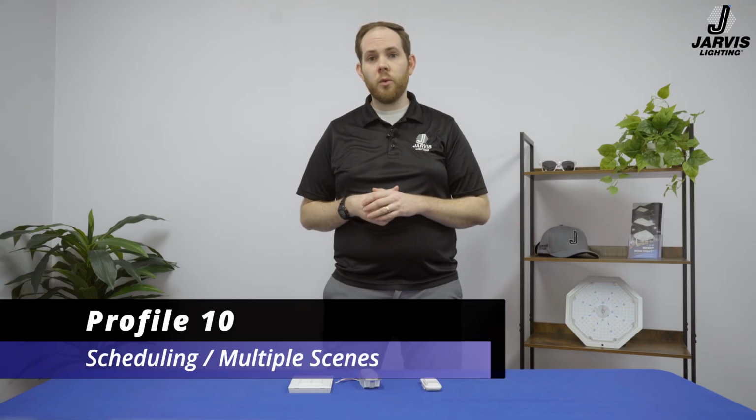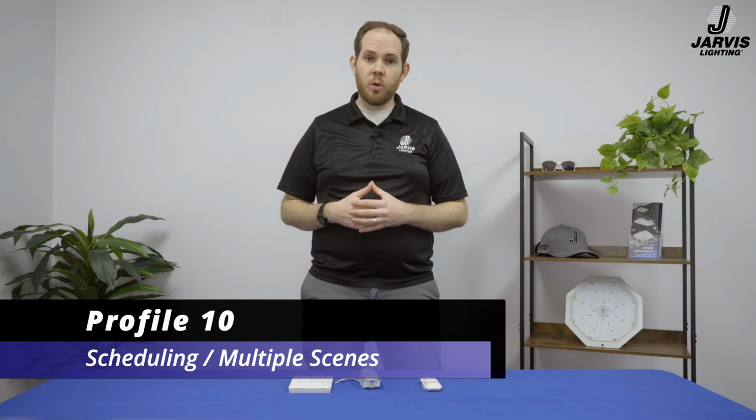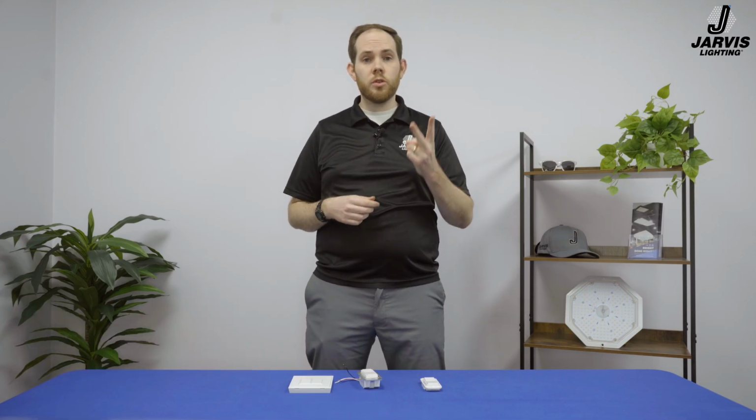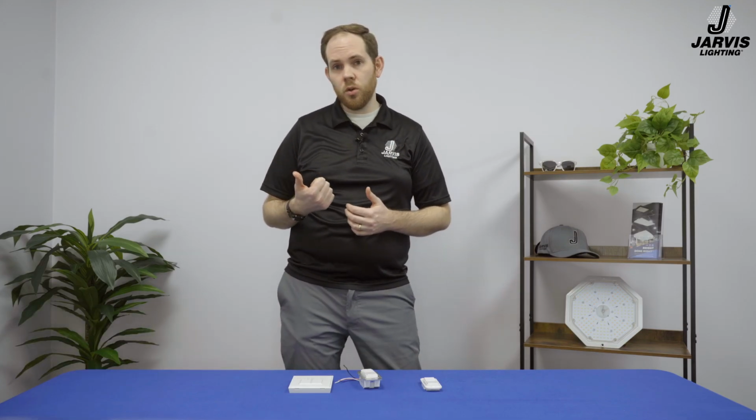The final default profile we offer on Jarvis Link is our scheduling scenes profile. This profile is commonly used for two different applications: preset scene control and scheduling. Both applications allow up to 4 preset scenes to be recalled via the Jarvis Link app, one of our 4-button wall switches, or a specific schedule. Preset scene control is commonly used in event spaces and conference rooms. Our 4 preset scenes are as follows: 100% on, off, 30% on, and occupancy dimming to 30% after 15 minutes without motion, and turning off after an additional 5 minutes without motion.